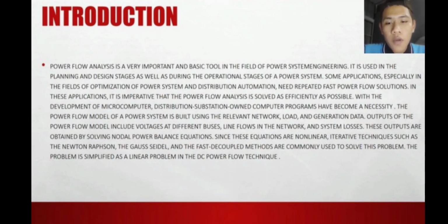The power flow model of a power system is built using the relevant network, load and generation data. Outputs of the power flow model include voltage at different buses, line flow in the network, and system losses. The outputs are obtained by solving nodal power balance equations.